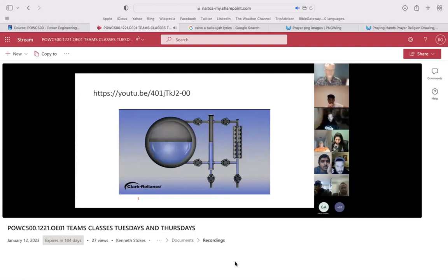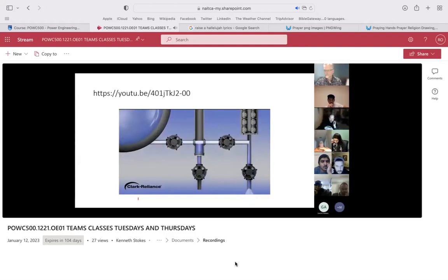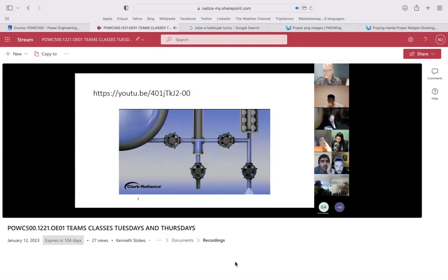Simply opening and closing the drain valve on a level instrument to conduct a blowdown will not ensure that water is flowing freely from the boiler drum through the water piping to the level instrument. By conducting the blowdown in this manner, the water that is in the instrument will drop and go out the drain, but there is no assurance the water leg piping between the boiler drum and the level instrument has been flushed. This is because the steam and water are both flowing from the outlet of the open drain.